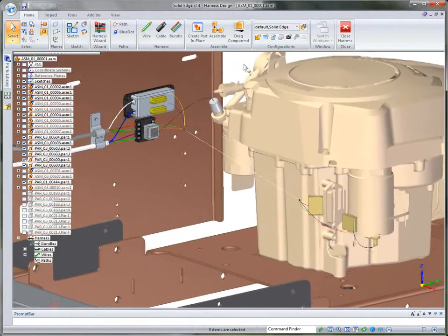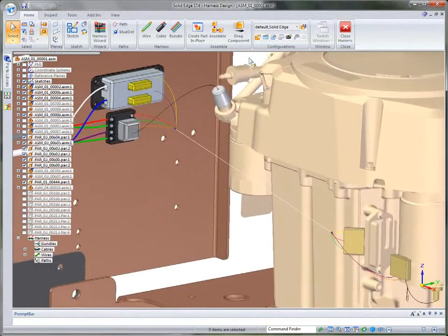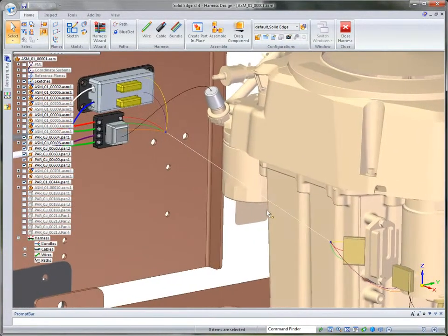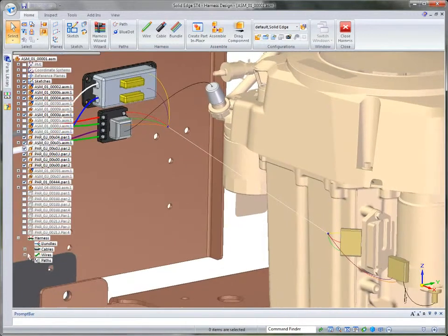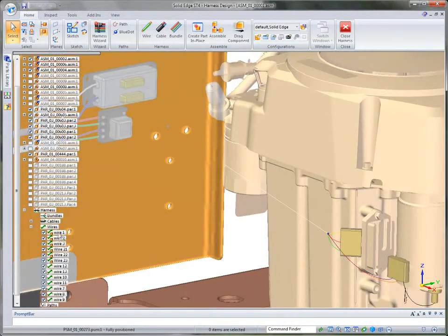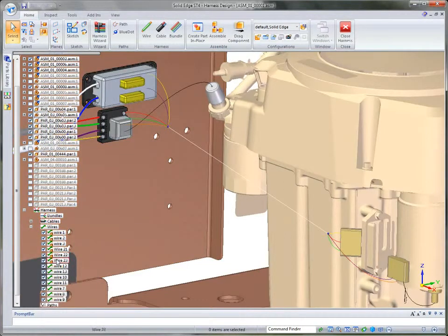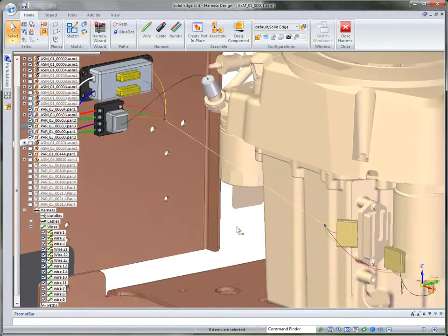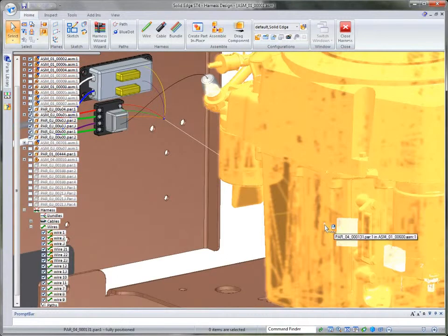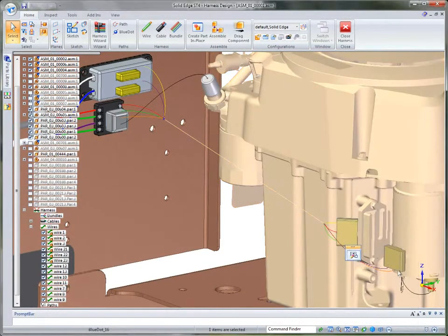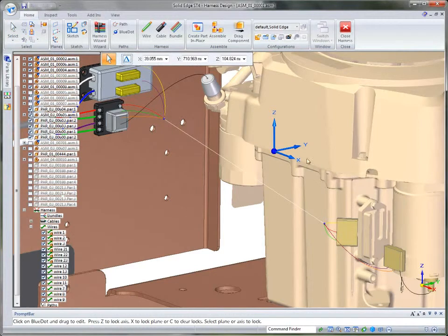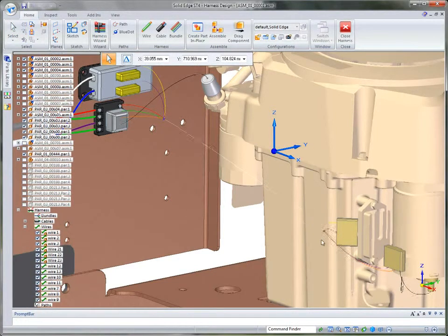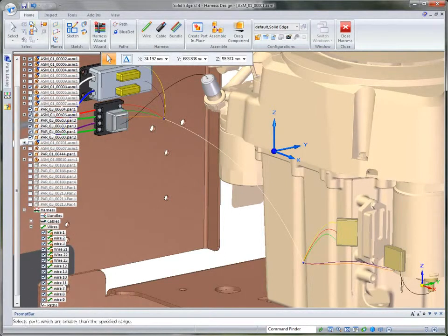Now you'll notice that when it creates this particular cable from the harness wizard, it also gave us the blue dots. And if I open up these wires, you'll notice that it shows us which wires go where, and it highlights them as I go across those wires. And if I want to make any changes to this, how do we do it? Well, there's the blue dot. So if I right mouse button click and go to that blue dot and simply edit it, you'll notice I can grab it and maybe adjust it down. And notice how the wires will automatically adjust as I select them.